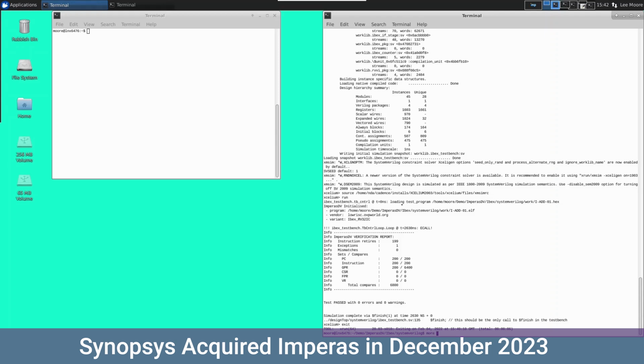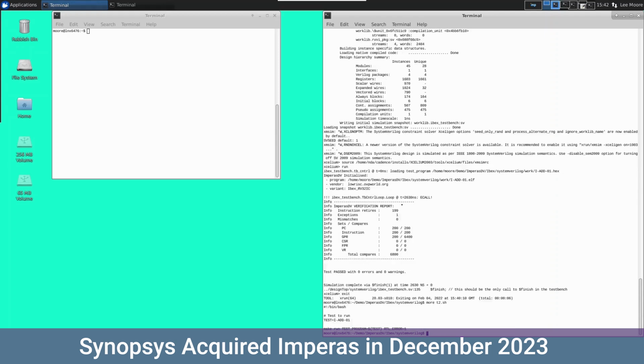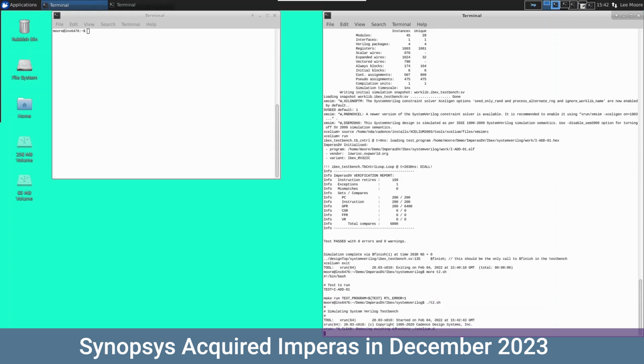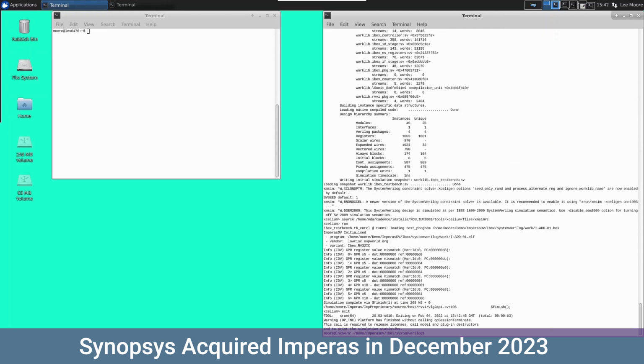So let's just have a look at the script that we're going to run here. As I mentioned, we've got this tick define that's going to be enabled. And if I now run this, let's see what happens at this point. Again, we go through the elaboration phase. I've actually got this configured at the moment to tolerate 5 miscompares, and this is programmatic. We can say how many we want it to absorb before it goes through to a bailout condition.